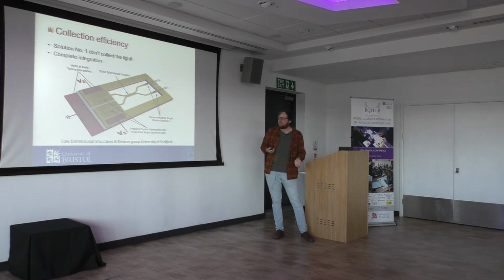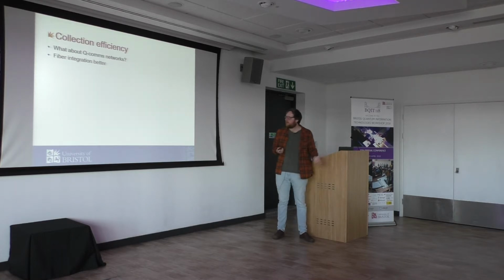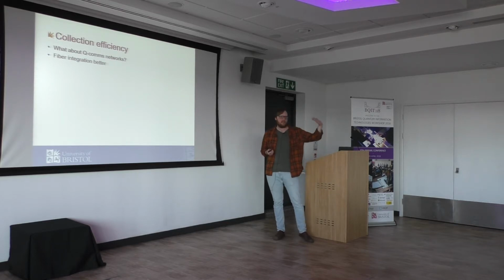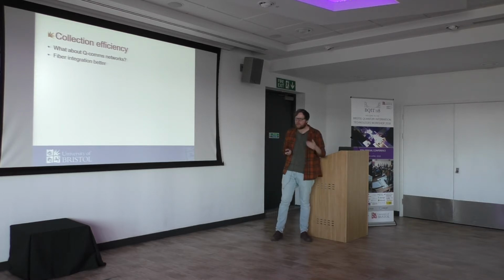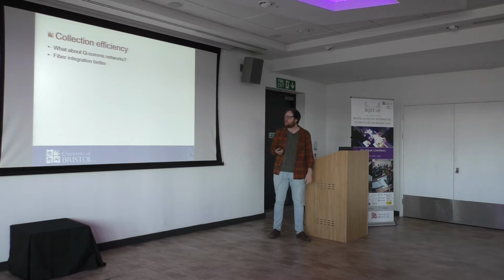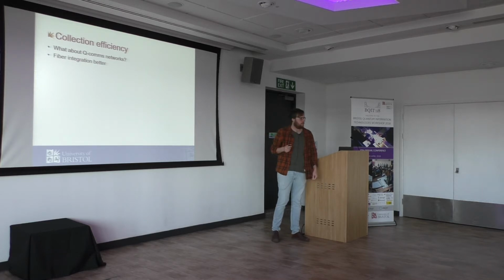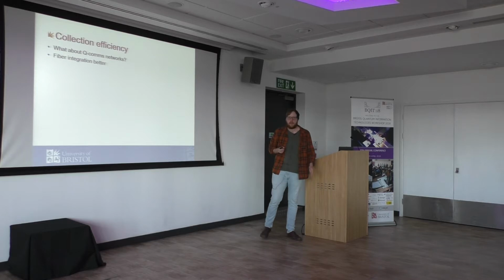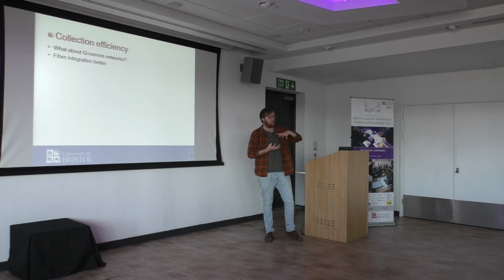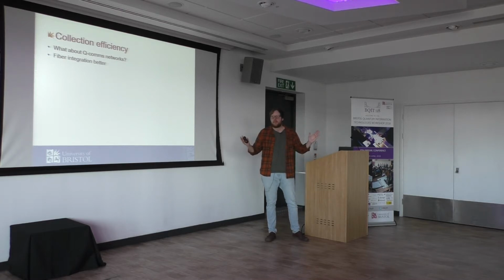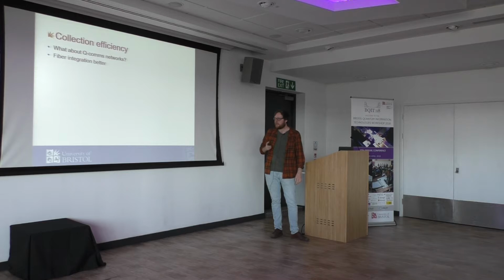But there are certain instances where you might like to go off chip. Mete gave a very good example in his talk, which is what about if you want to communicate quantum information over larger distances and you want to build a quantum communication network. There perhaps you might want to do some off-chip communication, so maybe fiber integration is better. But you can't just go to the Thorlabs catalogue and buy an optical fiber and glue it to the top of your photonic structure and hope that it's going to work. The refractive index contrast alone between gallium arsenide and most glass fibers makes that really difficult, before you even take into account numerical apertures and mode matching and things like that.